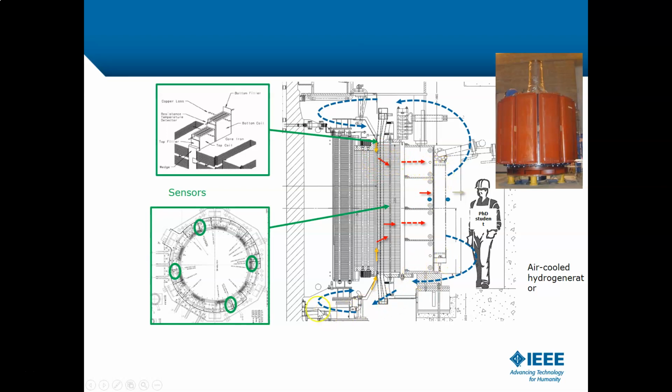And the same is also below. So this is the cooling circuit or the heating circuit for this system. And we have sensors, as I said, located around in these rubber bars between them. And we also sometimes have sensors in the stator yoke, as you say, the core out here, mounted into the machine. Here you can see the stator yoke pointed out where it is, and also the stator teeth here.